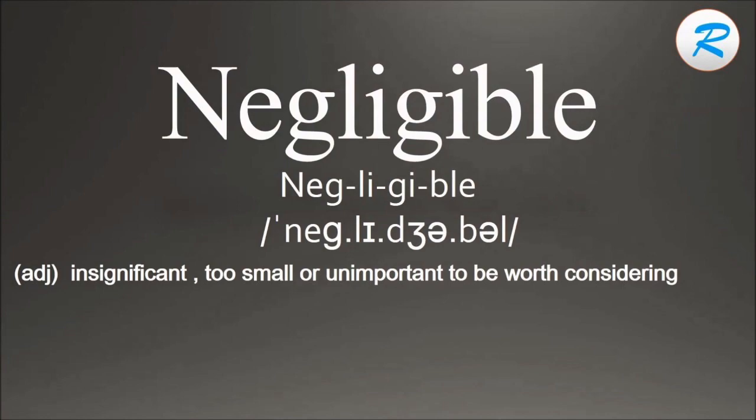So let's say I have a 480 volt bolted fault and my resistance is 0.01 ohms. So on your calculator, I equals E over R. 480 volts divided by 0.01, the answer is 48,000 amps.